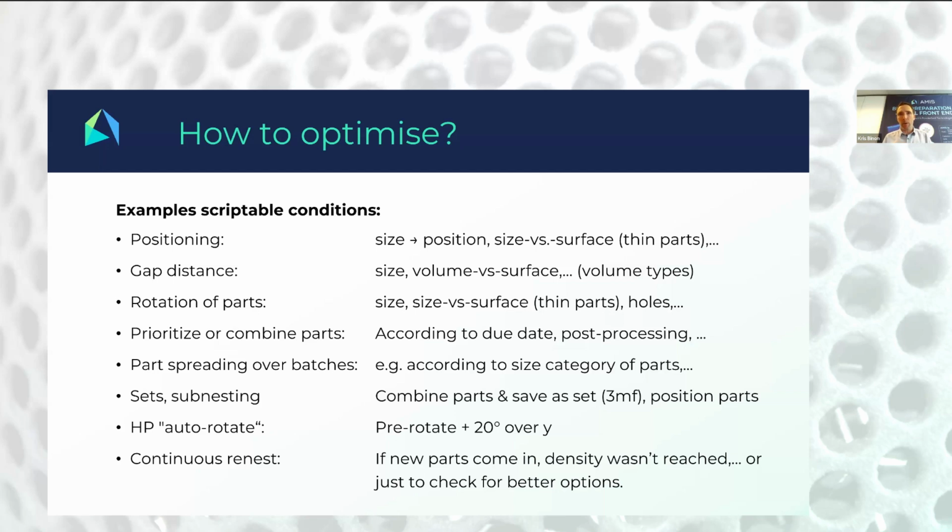That's going to have an impact on quality. That's going to have an impact on return on investment, or cost per part in general. So it's logical that you preferably want some good mixes. If you can spread out your big parts throughout different batches, you have the ability to add more smaller parts, and having a neater mix of the two, and so coming to better nests in general.